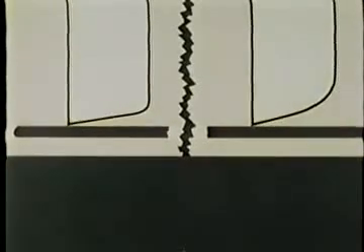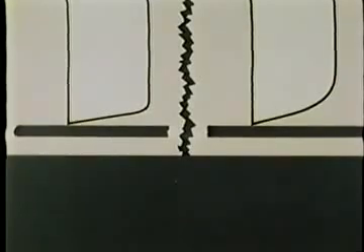Because there is no vorticity upstream of the plate, and because the circulation per unit length along it is constant, we conclude that all of the vorticity is generated along its length. Upstream, 95% of the total vorticity is contained within this area. Downstream, 95% of the total vorticity is contained within this area.